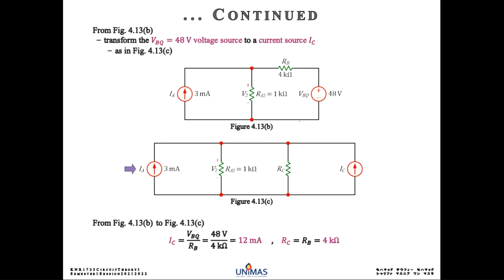Alright, so what I wanted to explain earlier is that between these two, the voltage is the same. Correct? V2 is the voltage also across RC. So what I said earlier was that you cannot combine because RA2 is the one you want to find, but now you can combine because the voltage across it is the same. So V2, RA2 and RC can be combined together.